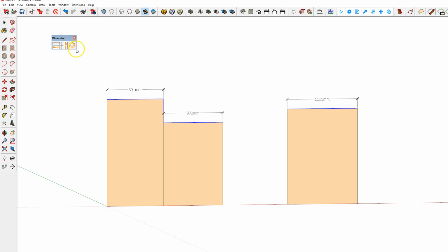To change that, you go into your settings, and in here I can put in 300, so it's double the distance. Click OK. I can click the button again and then again, and now it's updated. If I want these measurements to be aligned, it's very simple. I press the minus sign and press enter, and it aligns them. So this speeds up the process.